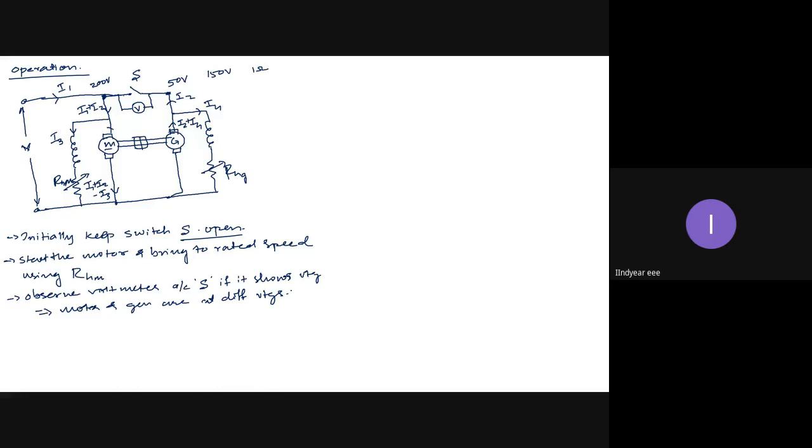We did that with some other technique, but what we were actually doing was matching all the attributes of the incoming power with respect to the bus bar power: voltage, phase sequence, frequency. These are the attributes of any AC power. When they are matched, only then can I connect to the same node.